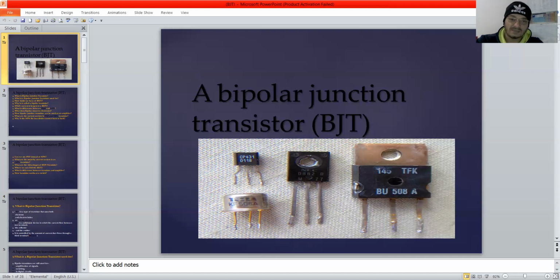This middle wire acts as the base of this BJT. Because the arrow goes inward, this means PNP. Here is the emitter, here the collector, here the base, and there is a relation in the current equation between the collector current and the emitter current.